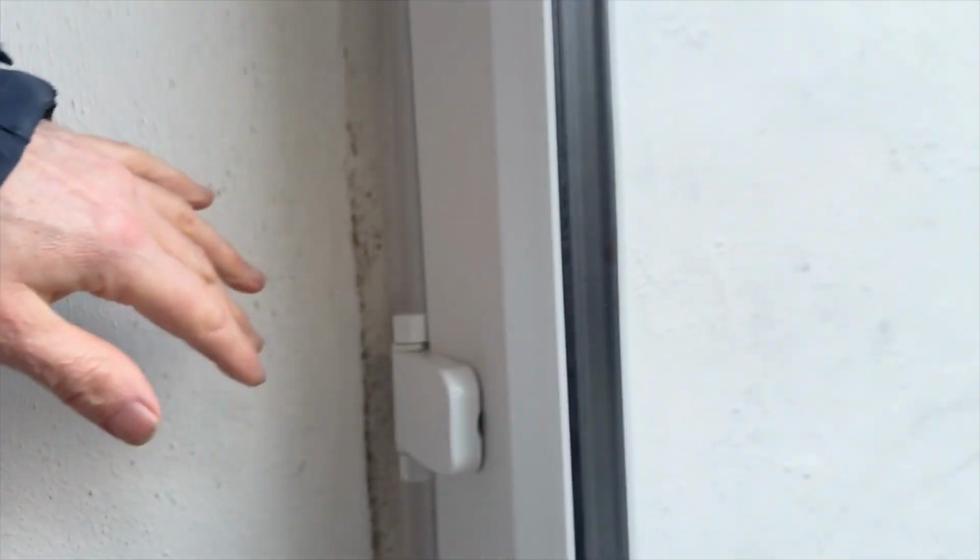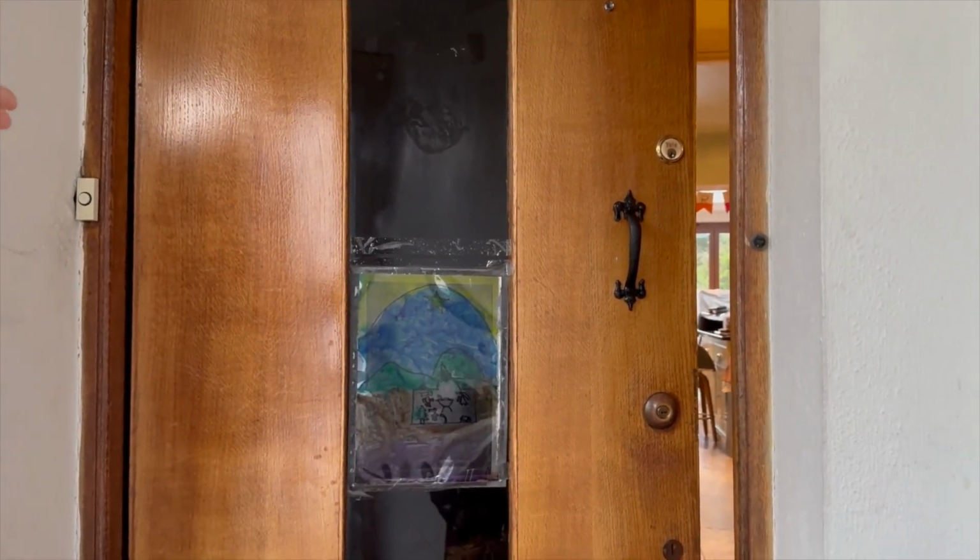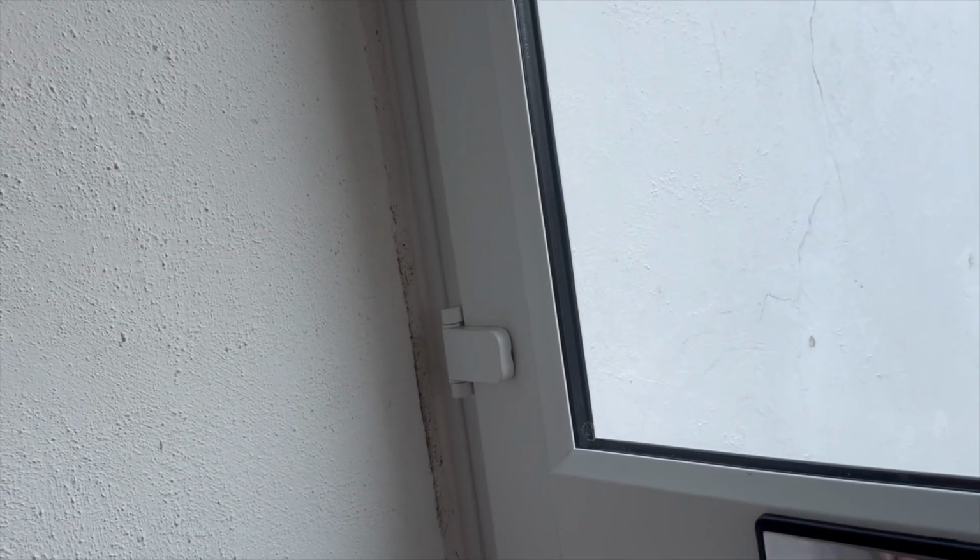But as a general rule, if you've got mould all over the place, then excess vapour is your primary issue. So you're getting mould in here as well, and that's because the porch is essentially unheated. Every time the front door's open, the vapour will get in, so that increases the risk of mould. Mould grows where relative humidity goes above 85% for long periods of time. So you're getting the vapour from inside, but it goes cold.